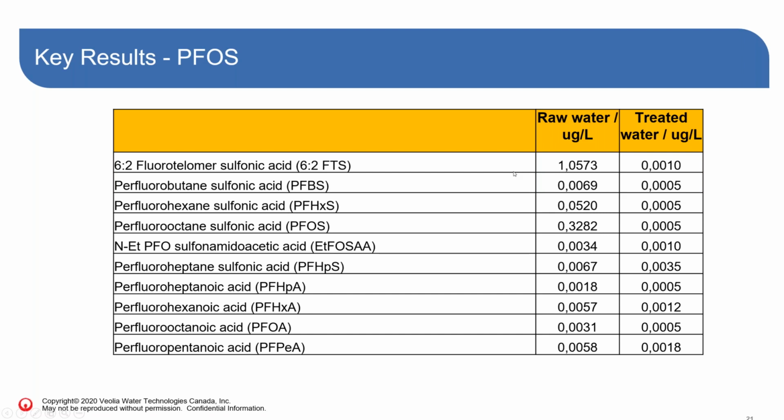That was interesting because we found that even if the plant was not designed for PFAS or PFOS removal, we are actually removing quite a lot of the perfluoro organics. And it's a combination of both the coagulation in the first ActiveFlow and the activated carbon in the ActiCarb system downstream.